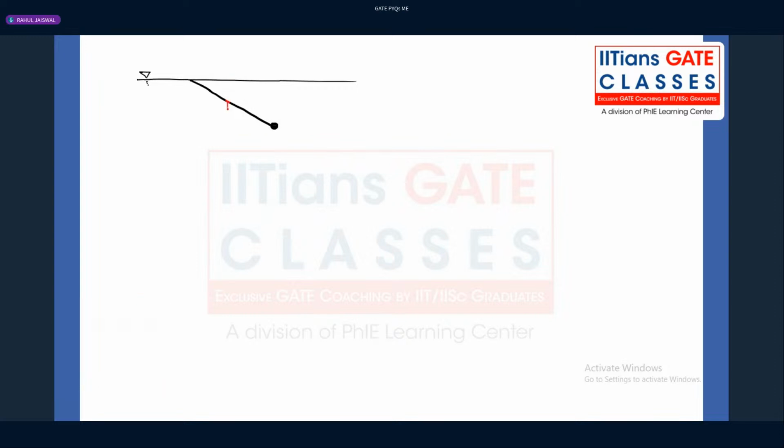First of all, that is the weight of the rod. Weight of the rod is acting in the downward direction. Weight of the ball is also acting in the downward direction. If it is in the fluid, there will be certain buoyancy forces. Here also there will be a certain amount of buoyancy force. It is hinged about a point A. For example, here in the problem they have mentioned a point A. So here I'm marking point A. And there is a liquid here.